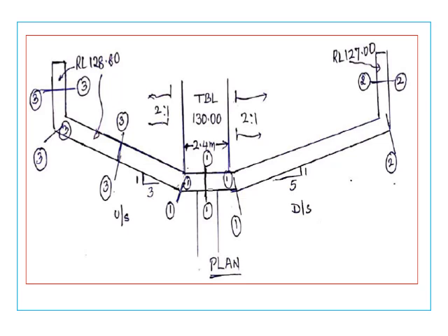Now when you come over to the upstream side, the water level goes to about 128.5. That is the maximum water level. Give a freeboard of about 0.3 meters to the maximum water level, so that comes to 128.8. Any wall has to be kept at 128.8. So now the wing wall is sloped from 130 here and goes down to 128.8. By the time it comes to section 3, it has already reached 128.8. So as you go with the slope of 2 is to 1, it will go below 128.8. That's the reason from section 3 you have to keep the top at 128.8.